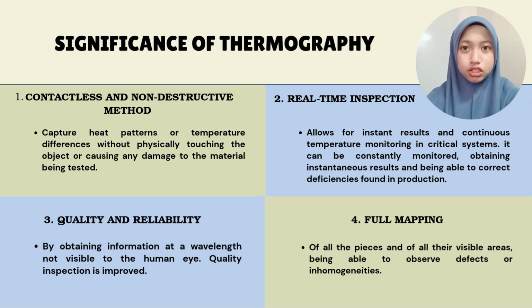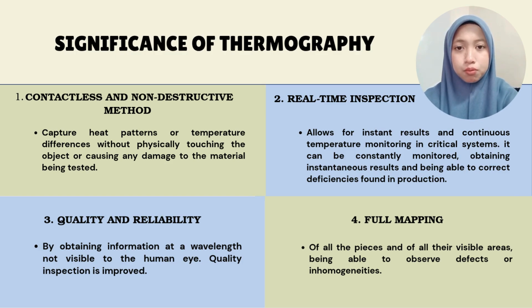Next, the significance of thermography. Number 1, contactless and non-destructive. This means thermography checks heat without touching the object, so there is no damage to the item being tested. Number 2, real-time inspection. It shows the temperature changes instantly. Problems can be found and fixed quickly. Number 3, high quality and reliability. It sees heat that our eyes can't see. This helps find hidden issues and improve the inspection. Number 4, full mapping. It checks the whole object or area. You can easily spot any unusual parts or defects.